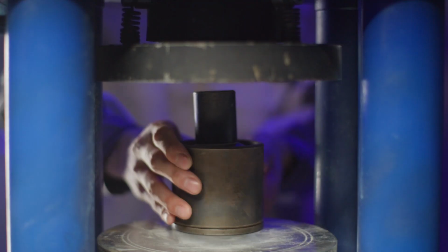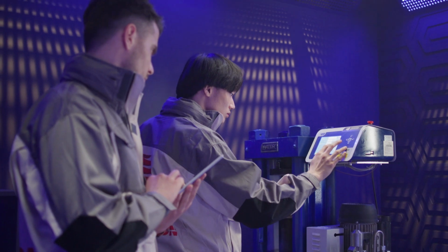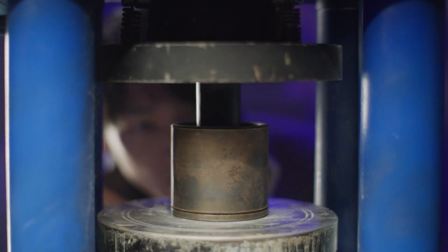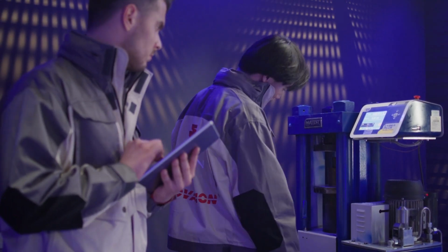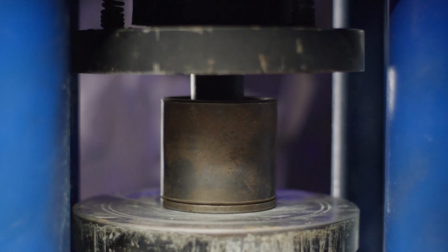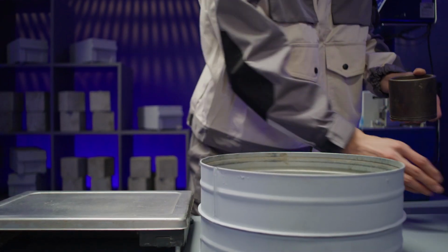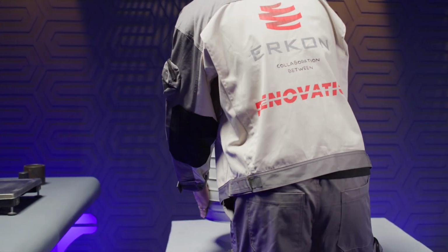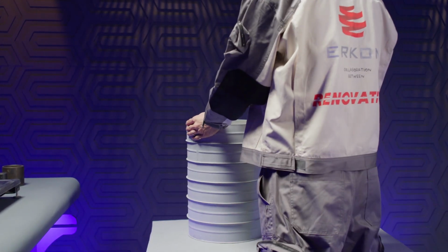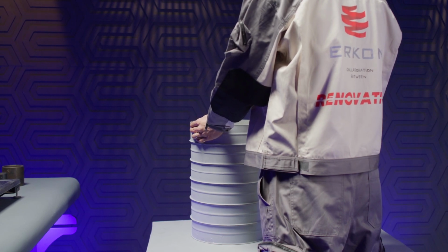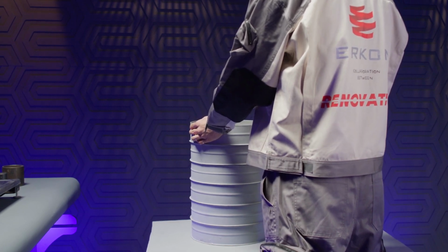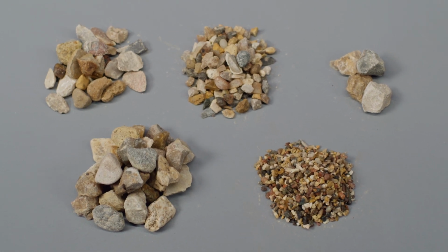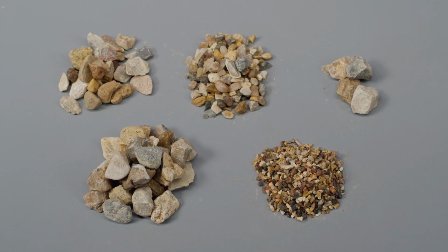So how do they do it? A sample of crushed stone is squeezed by a hydraulic press, gradually increasing the load. This test allows determining which strength class the aggregate belongs to. After that, crushed stone, like sand, is screened and the granulometric composition of the aggregate is calculated. When the proportions of certain fractions correspond to the required indicators, the raw materials are taken to work.